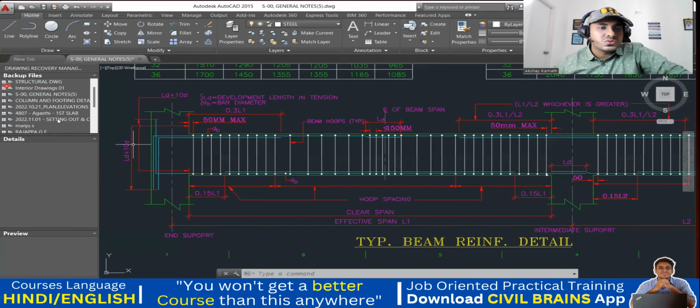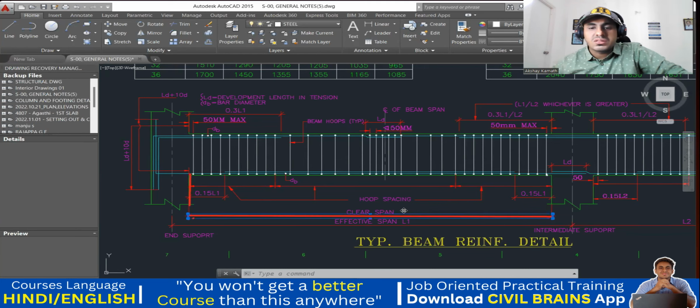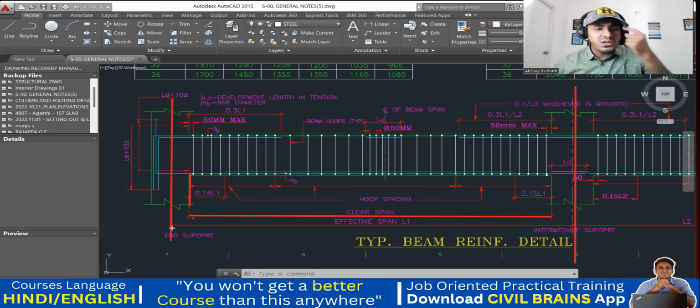See, this is clear span. Always remember, clear span is from this column inner to this column inner. And what is effective span? Effective span is always from the center of the column to the center of the column. If I measure, it becomes my effective span. Understood? Again, the same concept holds good here.